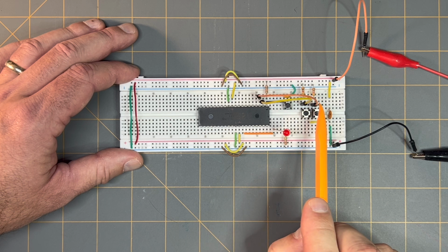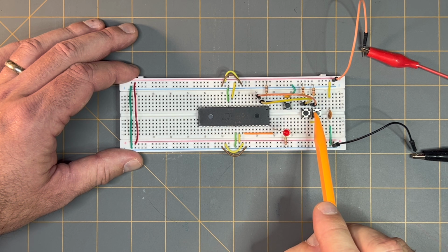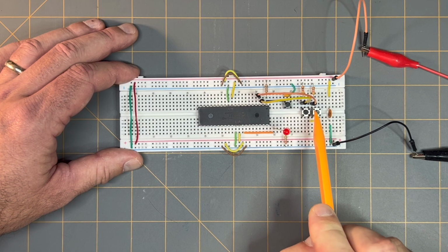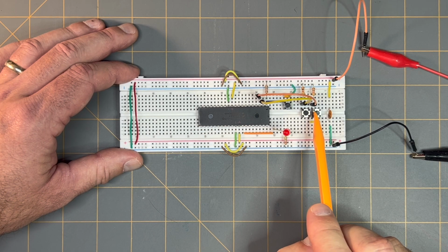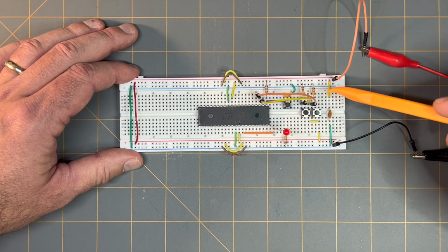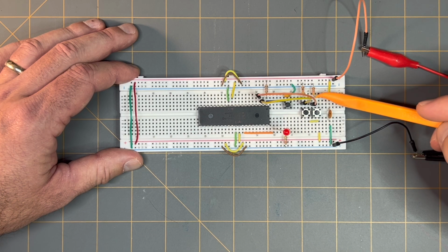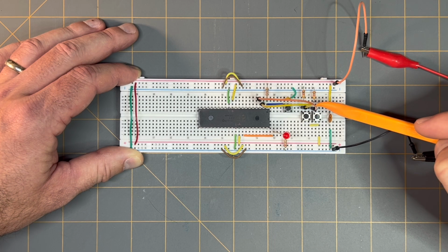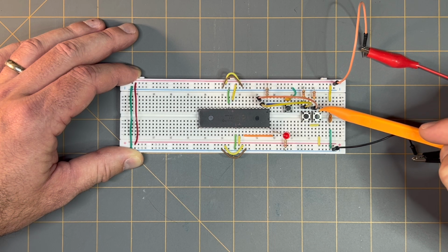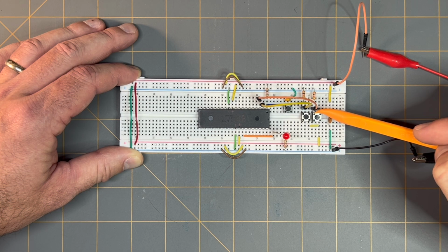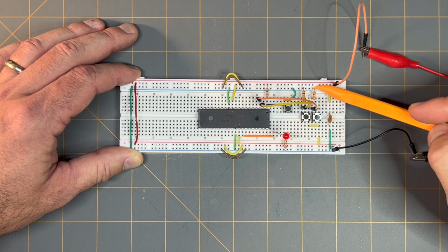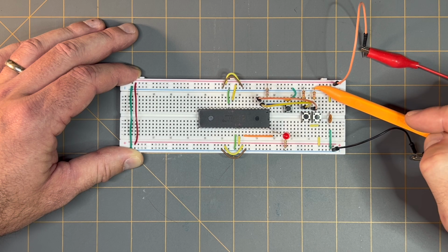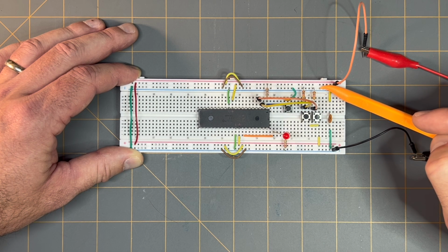The other end of that orange jumper wire goes to a point D9, which is in line with switch 2 at point E9. And again, I took another 1 kilo ohm resistor and placed one of its legs into point B9, which is in line with that orange jumper wire and also in line with switch 2. And the other leg of that 1 kilo ohm resistor is at an adjacent point on the negative power rail.